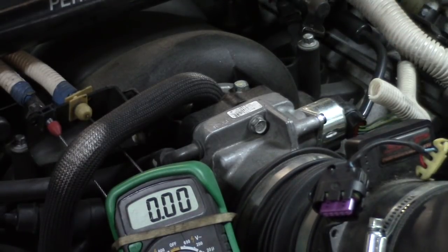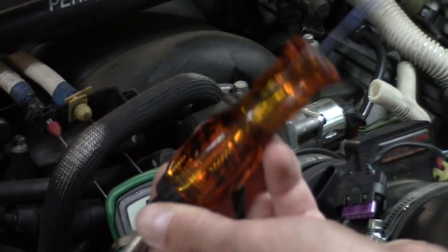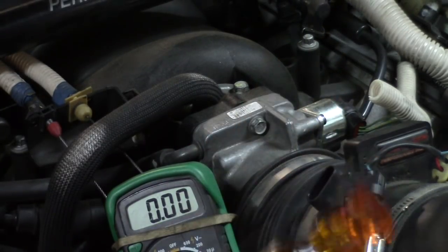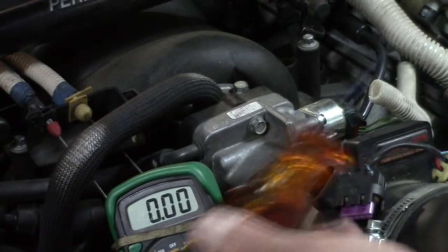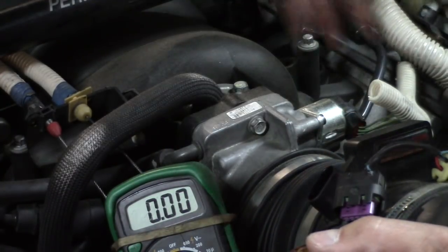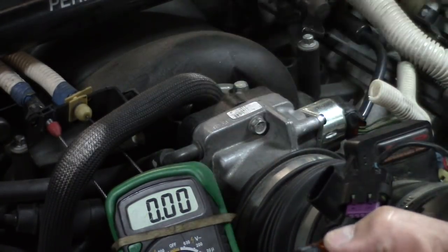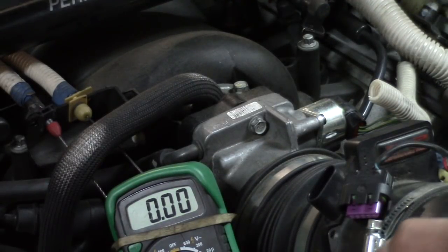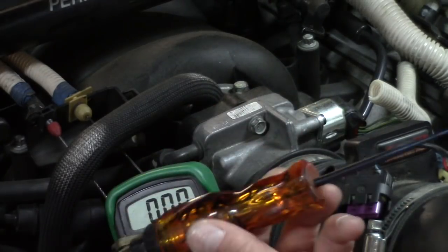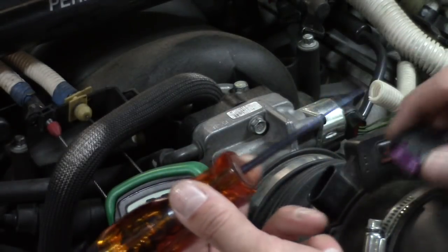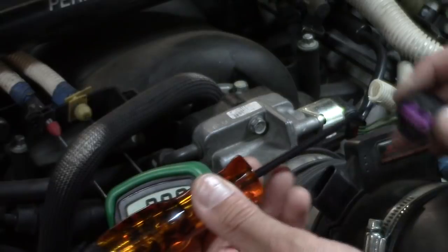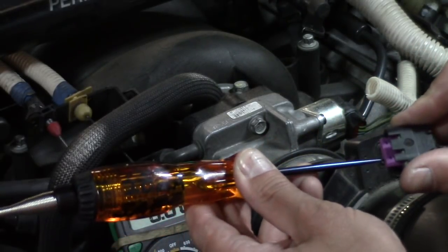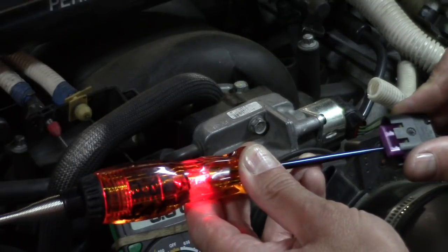So another way you can do that would be with a test light, and a lot of people are pointing out that I never use a test light in my videos, and can I start using a test light? I mean, there's really no difference here. I just like the voltmeter because I've got a lot more flexibility with just changing the dial to the various settings. But you can do a test light if you want. So I'll have my test light connected to the battery ground, and then I can just poke around until I find it light up. You can see hopefully right there in the camera that it does light up there.